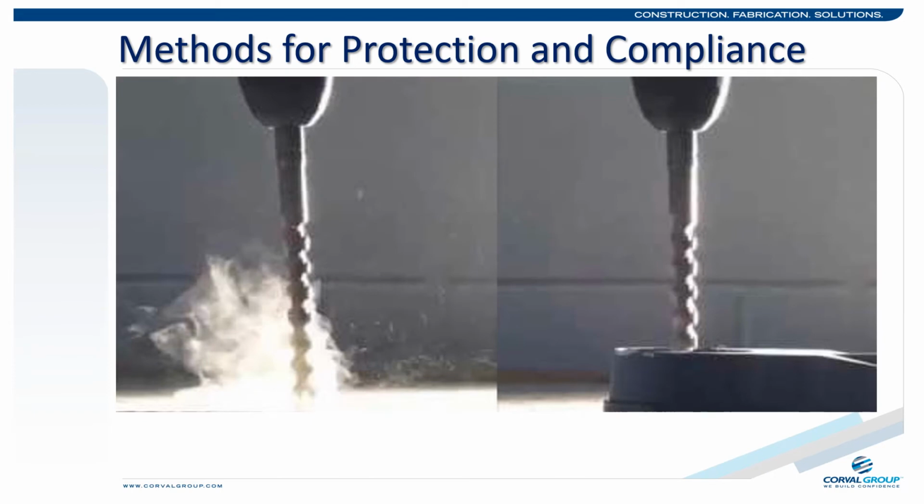Within Table 1 and the standard itself, you will see a control that is essentially removing the exposure by eliminating the respirable dusts. Two prominent methods are the wet methods and use of a HEPA-rated vacuum with appropriate attachments to capture and filter the dust. The photo on the right shows the drilling being performed through an ancillary shroud that collects the air and dusts at the point of impact. The shroud will typically have a fiber or whisker component that allows a range of drill bits to be used and will not be completely consumed with each drilling task.